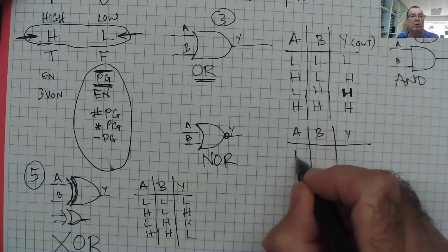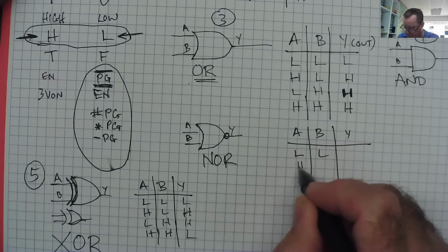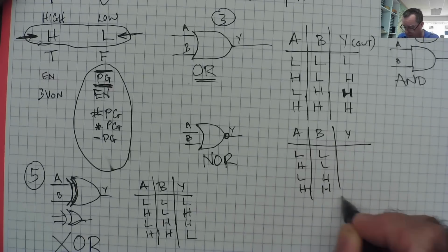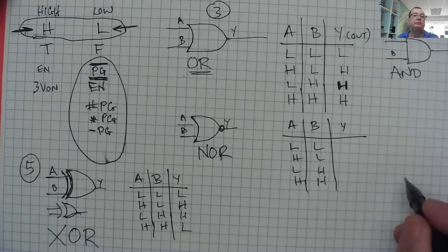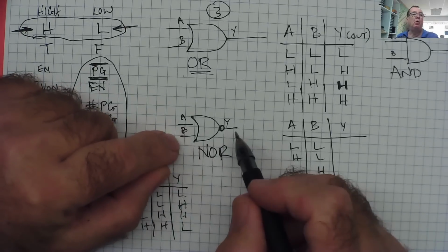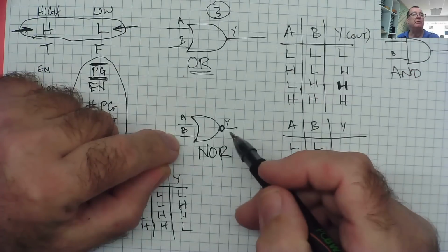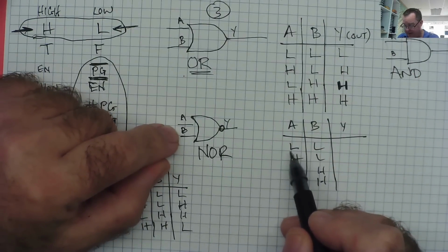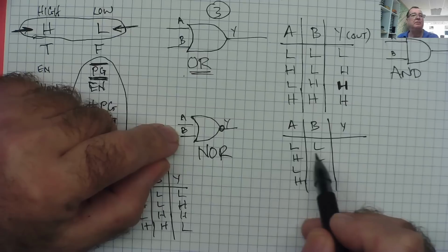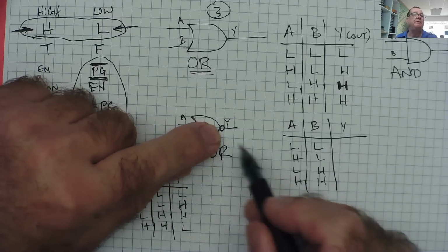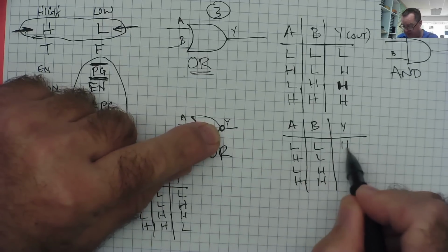We know there's only 4 combinations on all of them. That's the only possible combinations. Let's look at it like an OR gate, which we've just understood, with an inverter. Is A or B high? No, they're both low. So the output should be low, but the inverter inverts it, the output is high.